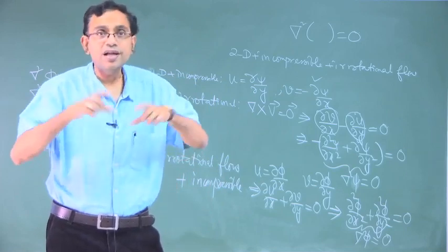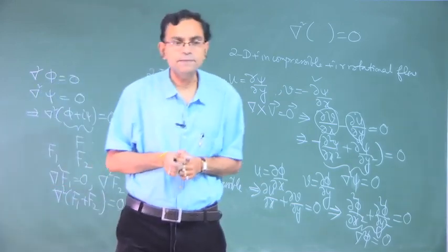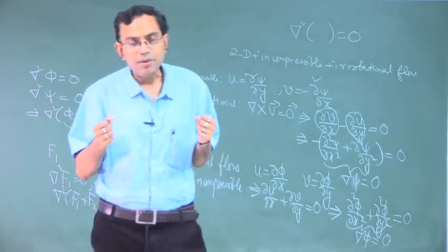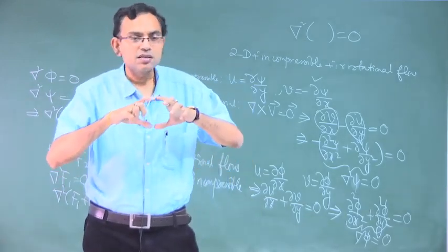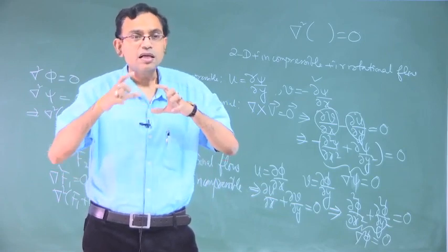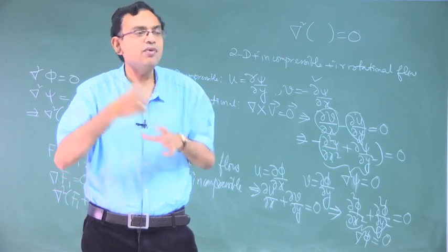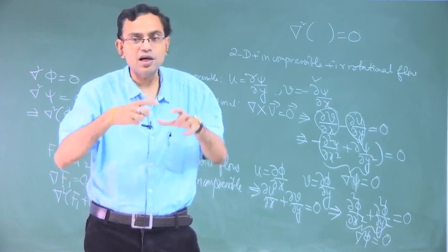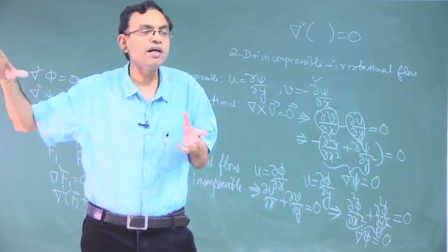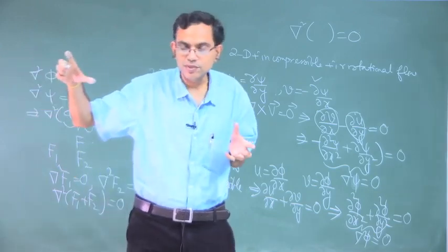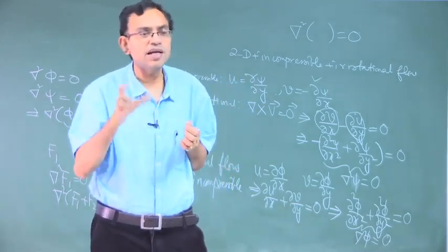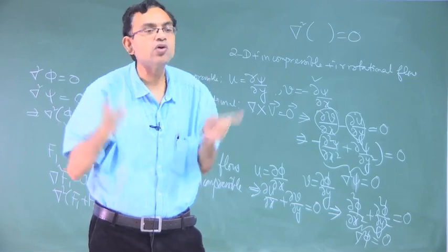So, what we may recognize out of here is that by obtaining stream functions we can also solve an inverse problem, that what could be the contour of a body past which the flow is being described by the stream function, because a special case of a stream function which say we will set as 0 will represent the contour of the body.